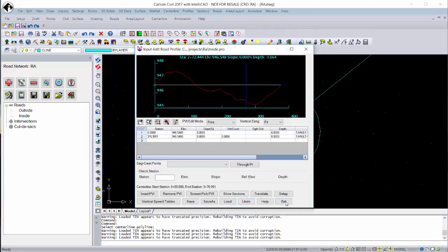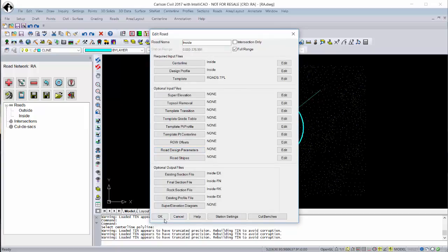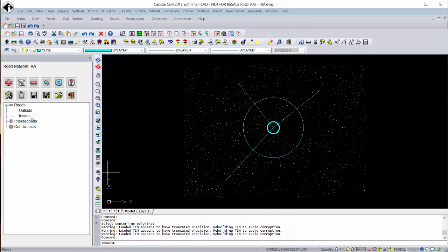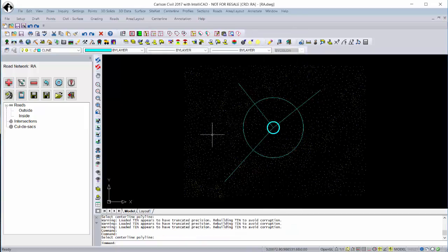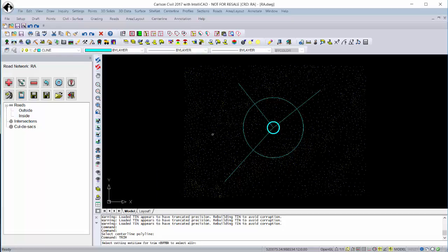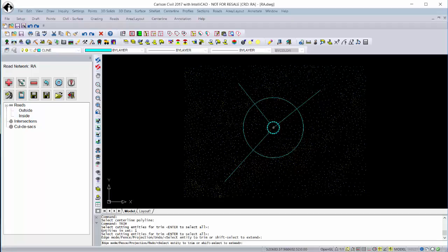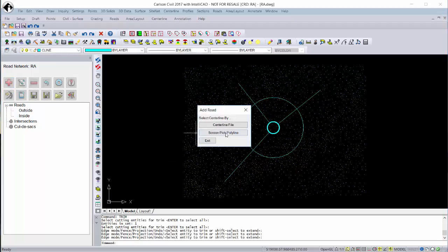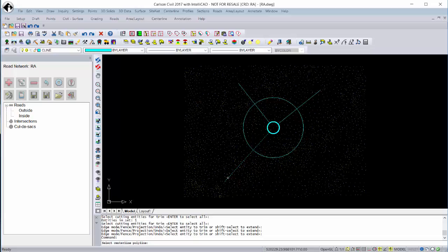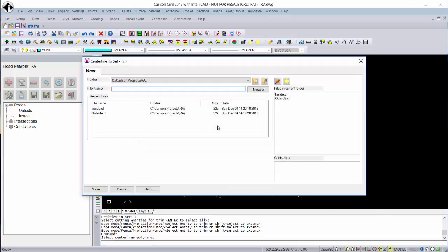We'll look at the profile quick here again, end to end. In this case, just a flat profile. And now we'll add those two streets in. First, we got to trim out the interior here. So we'll just run the trim command and select the inner circle and trim those two pieces out, or three pieces out. And now we'll just call these R1, R2, and R3 for these.